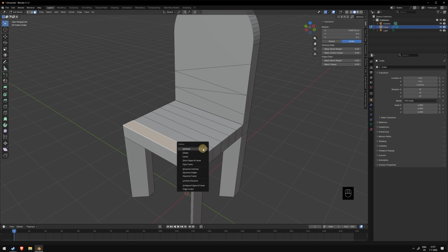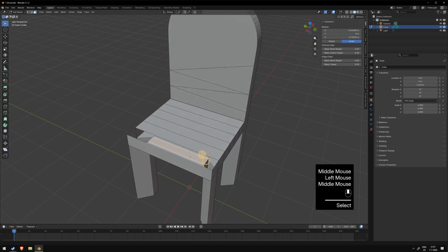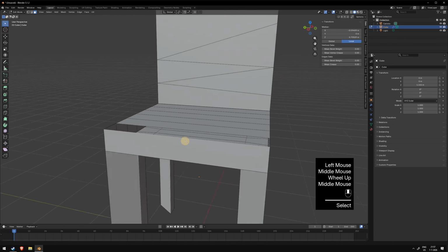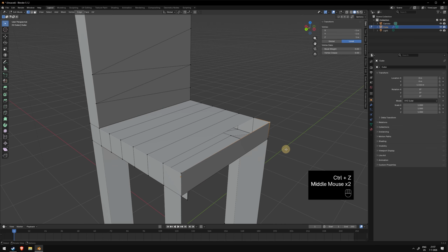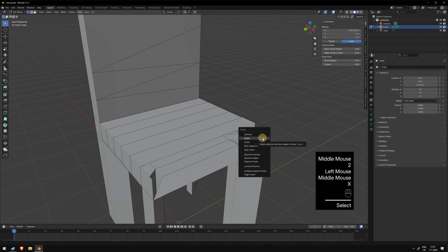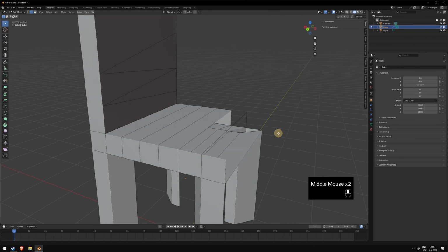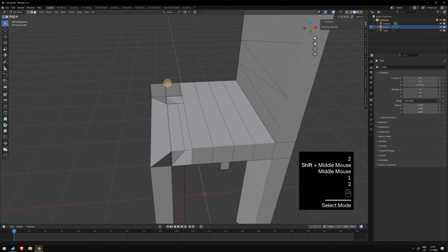For example, if I just wanted to delete the faces but leave all of the vertices intact, we can now look into our model after we have deleted only the face. If we wanted to delete the vertex exclusively, we can do that as well from this menu, and we can also, of course, delete the edges. Now, this has really messed up our geometry, so let's try to repair it without undoing our steps.